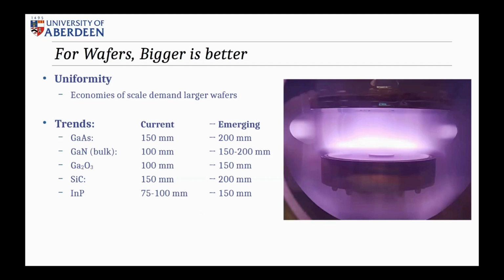Now, what you'll see here is a picture that's quite old now. This is a wafer inside a gaseous electronics cell in argon. The color contrast on the screen might not show it as well as I hoped, but hopefully you can see that there is a discharge on top of this very small wafer that is extremely inhomogeneous. You've got a glow in the middle and it tapers off towards the edge. So you've not got a particularly homogeneous plasma touching that wafer.